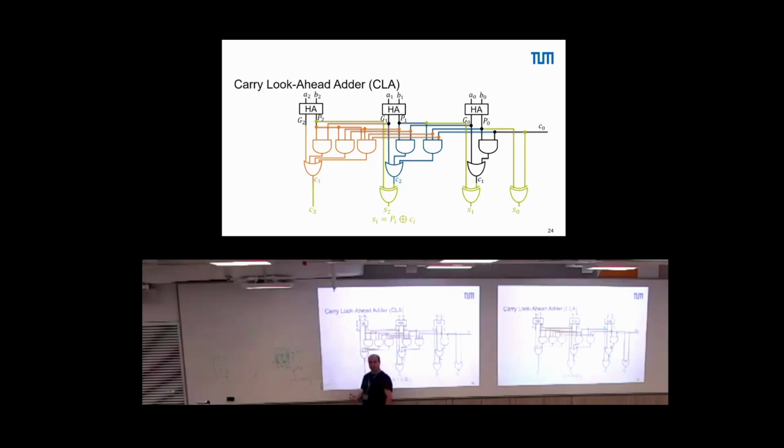What does this mean for our circuit, for the switching behavior? We switch approximately at VDD half. We settle at VDD. This here is time, meaning if our capacitor increases, our circuit gets slower, right? So large fan out is difficult because it makes our circuit slow.